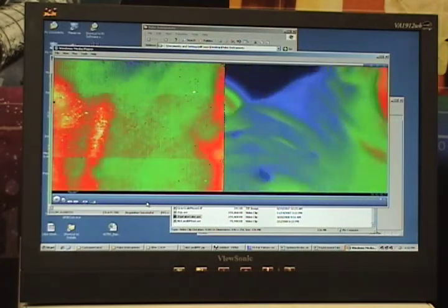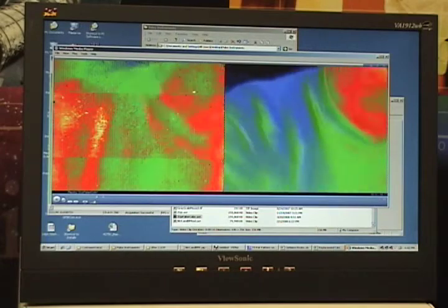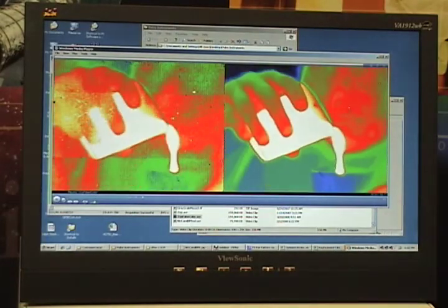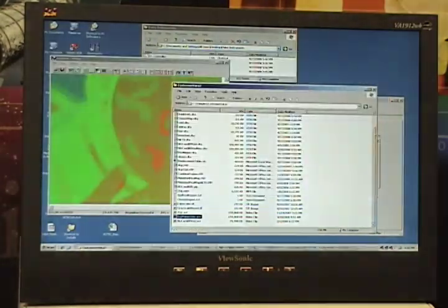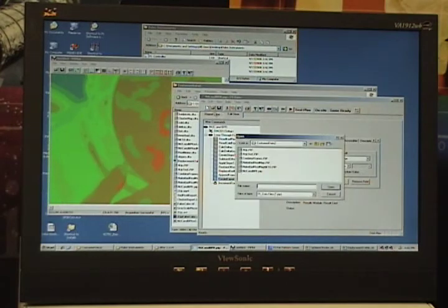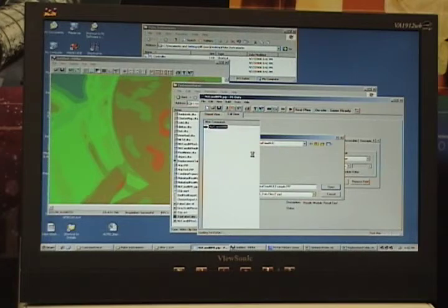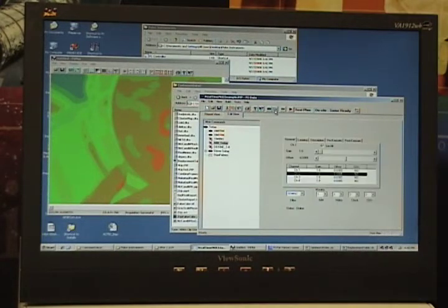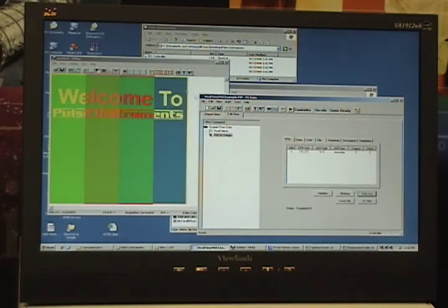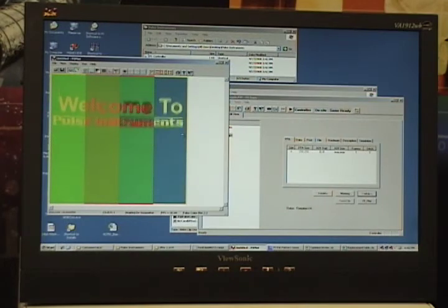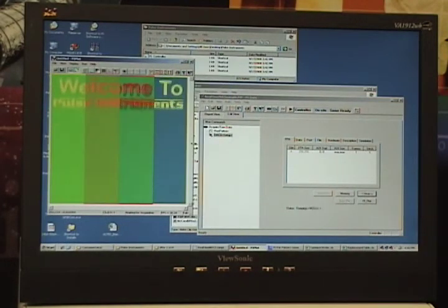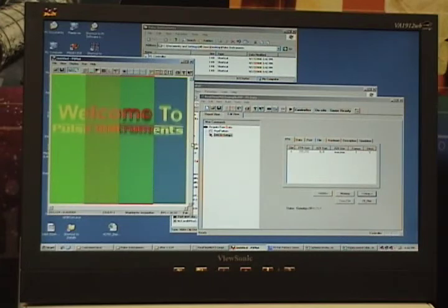All the video correction we've shown you thus far has been done in post-processing after the video was collected. We can also apply the correction in real time as we're acquiring live video. I'm going to use my test pattern again, but this time I'm going to program each of the 4 clock driver channels with different amplitudes and offsets to demonstrate offset and gain non-uniformity. As you can see, the image is very non-uniform.